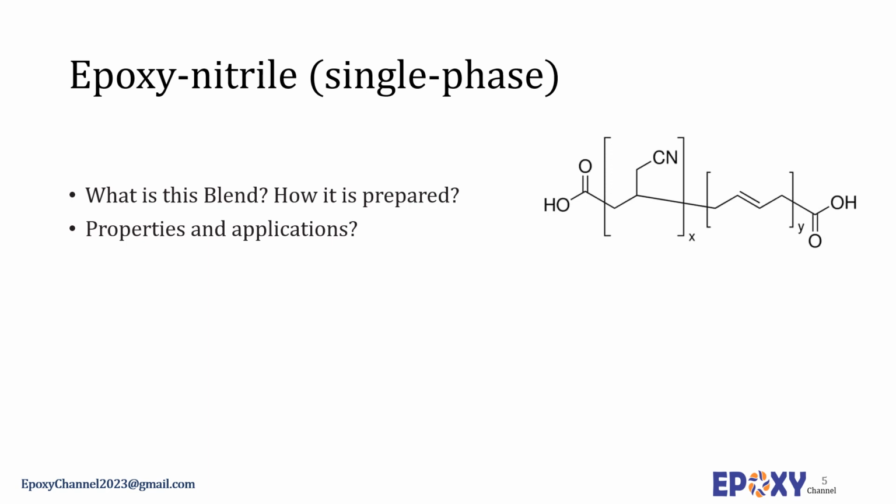These widely used synthetic rubbers feature flexibility and resistance to wear, mineral, silicone, synthetic oils, hydraulic fluids, and fuels. They are resilient and have low creep and superior abrasion resistance. Nitrile rubbers are commonly used in the automotive, marine, healthcare appliance, aerospace, and other industries. Specific applications include fuel lines, automotive transmission belts, rollers, water pump seals, hydraulic hoses, cable jacketing,